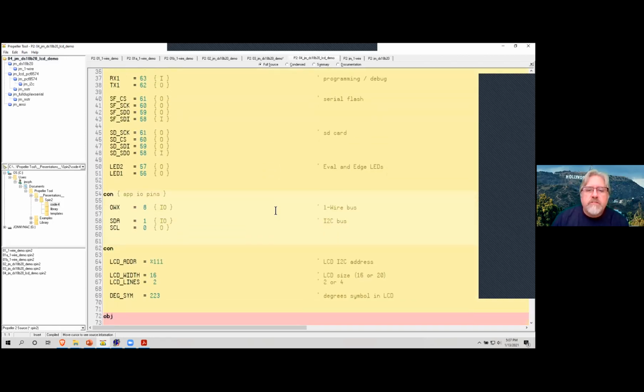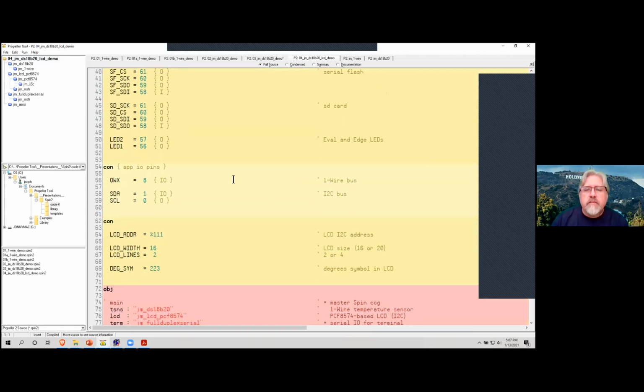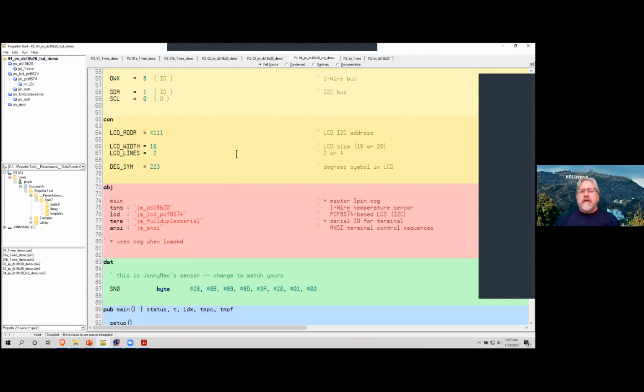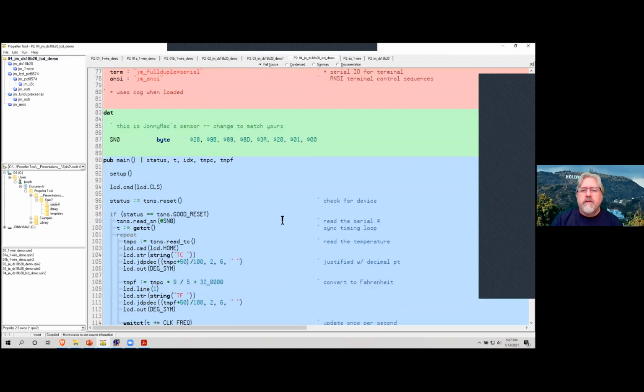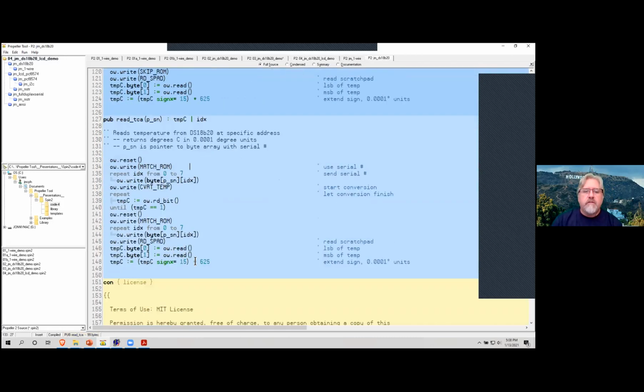All right. Any questions on OneWire? It's pretty straightforward. You just have to go through the data sheet. Now you don't have to go through the basics of the communication. You'll just look through the commands that you need to send the device, and typically the OneWire device is going to send you data back. You just need to know how that's formatted. But that's easily accomplished. The reading of the device is accomplished with the read feature. It's actually quite easy. You just have to organize your code around what the device wants to do.